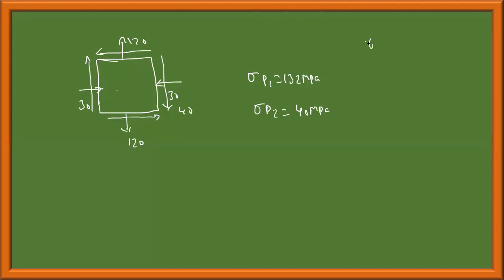If theta is equal to 10 degrees, in the Mohr circle it is 20 degrees, because the X face and Y face are 90 degrees apart here, whereas in the Mohr circle they are 180 degrees apart. It means that in the Mohr circle, whatever you get is represented in terms of 2 theta. So what we got is 2 theta P, which is equal to 151.93 degrees.